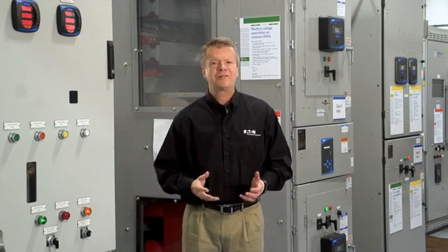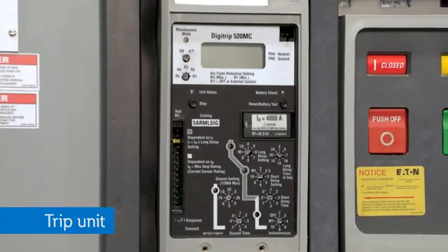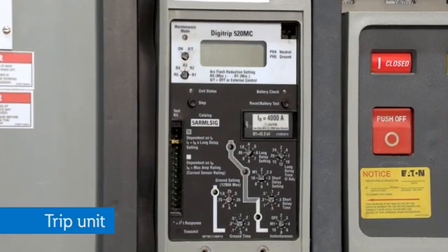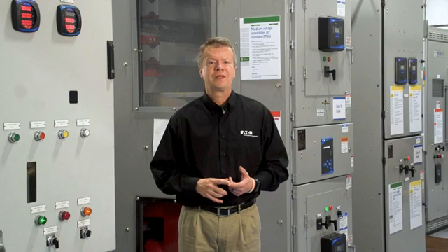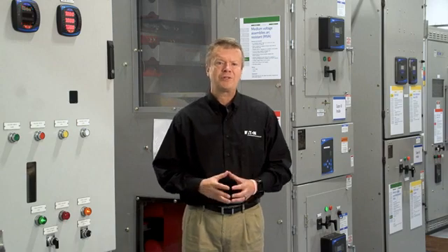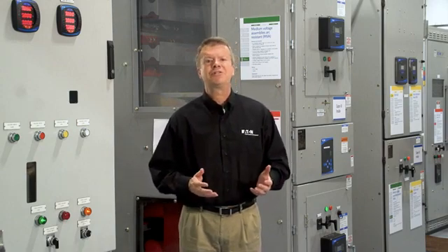All power breakers require some type of additional intelligence to operate. For low voltage breakers, this is typically a trip unit installed in the front of the breaker. Trip units may include long, short, instantaneous, and ground fault protection. They may also have arc flash protection built in with a maintenance mode setting. Eaton's low voltage power circuit breakers are these Magnum and NRX breakers. These breakers use either Digitrip or PXR trip units.